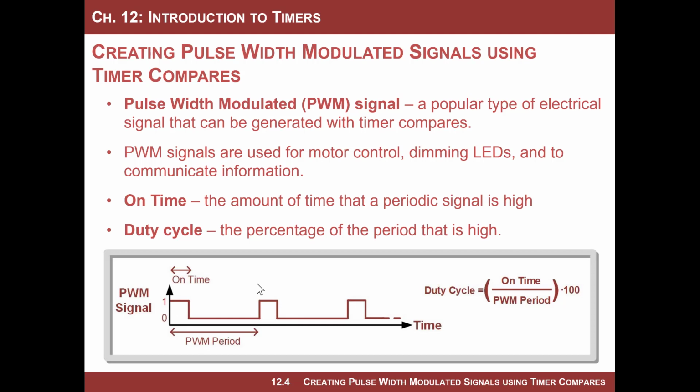The reason these are used as control signals is very interesting, because with one signal, like a motor, you can have a PWM duty cycle that you send to the motor, and that tells it to stay still. And then as you widen the PWM period, it'll start spinning maybe to the left. And then if you shrink it, it'll spin to the right. And so it's just a control signal.